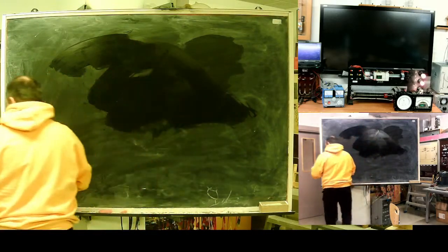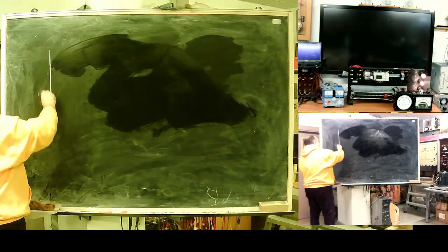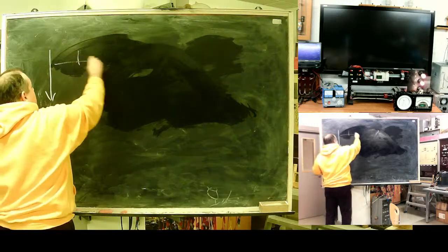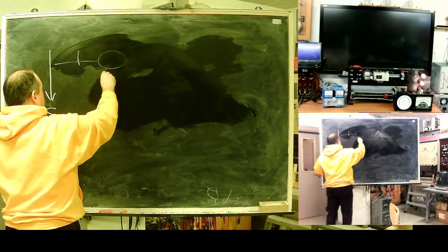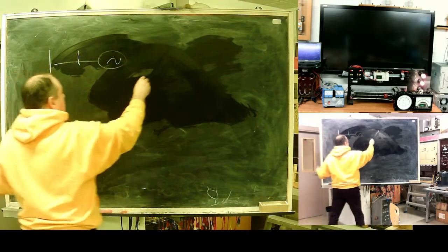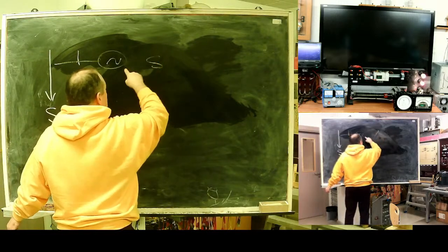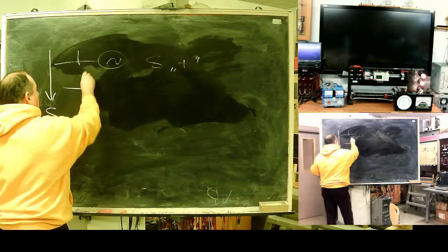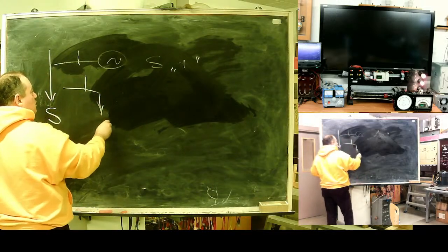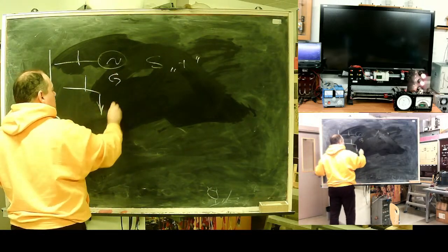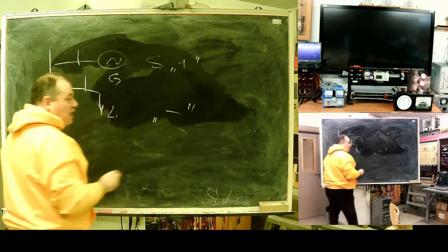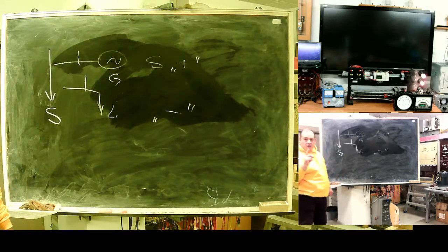So my trick will be: I will compose a vector of power in the nodes where generators are connected. I will write the power with the plus sign. On the nodes where loads are connected, I will write its power with the minus sign. Power, not current, but power.